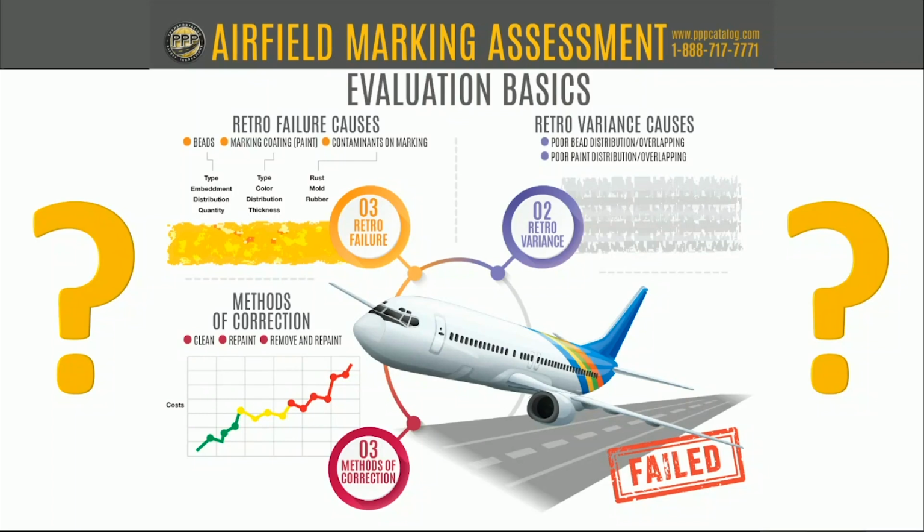Yeah, good information, Greg. Just to clarify, the type of thermoplastic that Greg was just referring to, that's 90 mils, 120 mils very often on the roadways, is a die-extruded product. That is not approved for use on airfields. When we talk about thermoplastic, we're talking about the preformed thermoplastic variety.